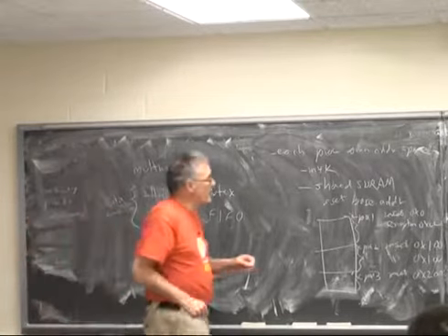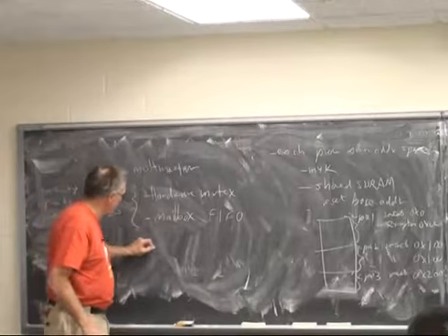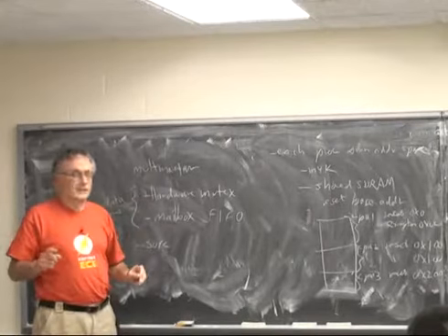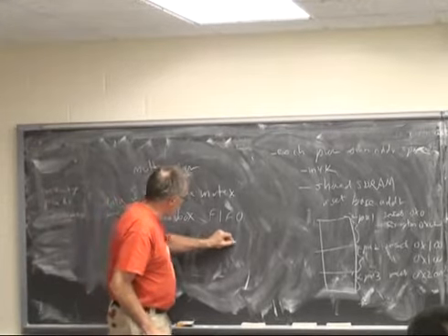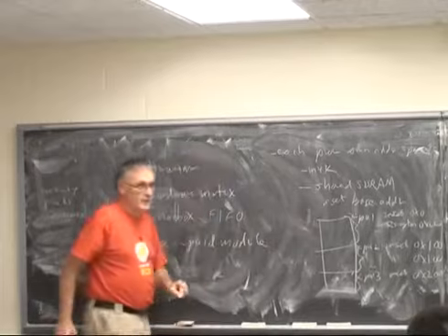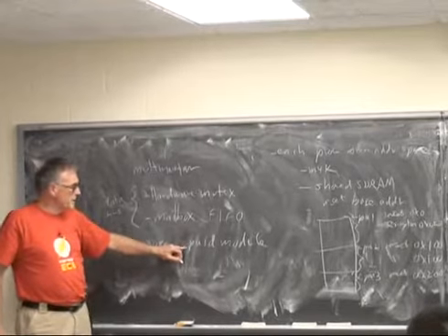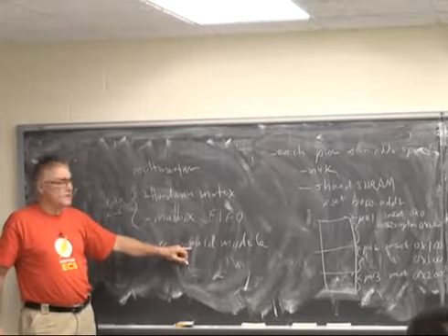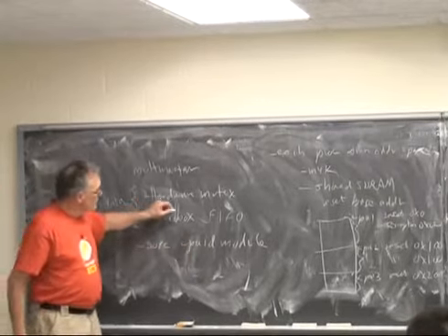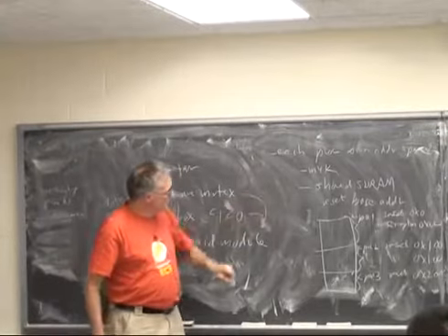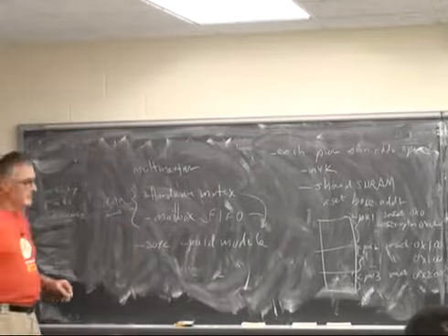Yes, there is a SOPC Builder entity that you want to add, which is a CPU ID module. I can't remember if it's on SOPC or part of the CPU ID description, but you want to make sure that the CPU IDs are set up so that each CPU you define has a unique ID, because both of these will use the ID which is picked up from the CPU ID module.